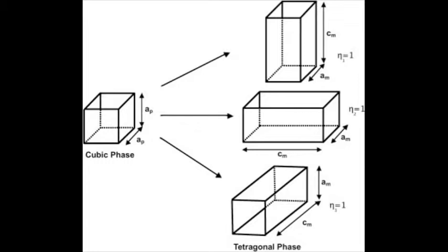As I stated before, this martensite transformation is a diffusionless one. Instead, there is a sudden shift in the crystal structure that occurs. The face-centered cubic structure of the austenite rapidly changes to a body-centered tetragonal shape of the martensite. Due to fast cooling, diffusion is extremely restricted. This leaves the carbon atoms with nowhere to go. To make room for them, the lattice must stretch out in one crystal direction. This elongation in turn causes strain on the crystal structure. This strain is what gives martensite its high hardness values. It also accounts for the brittleness of the structure.